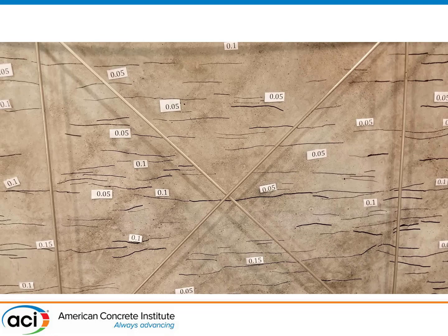After cracking, we were... unusual for me, I'm new to UHPFRC. I'm more of a regular concrete person, so to speak. And the fibers totally changed the behavior from my expectations. We had not a contiguous crack going across at all after cracking had occurred. So significant numbers of small cracks.